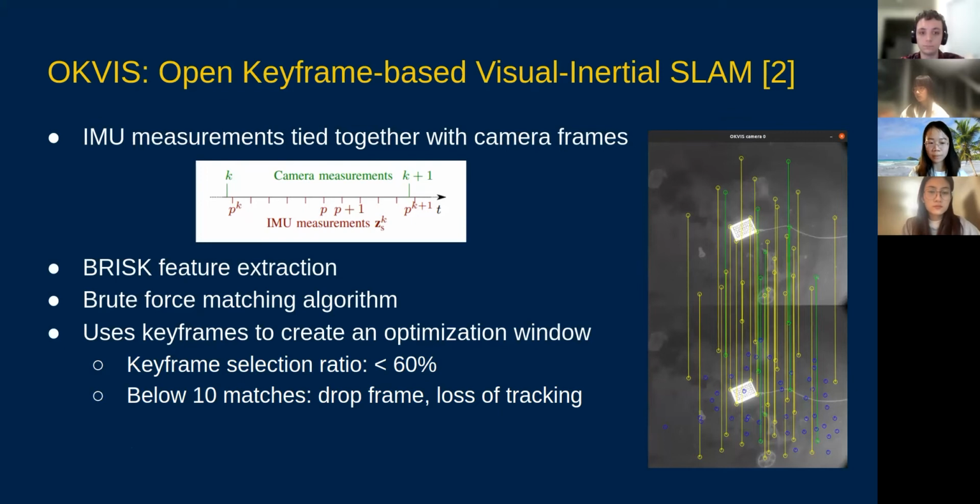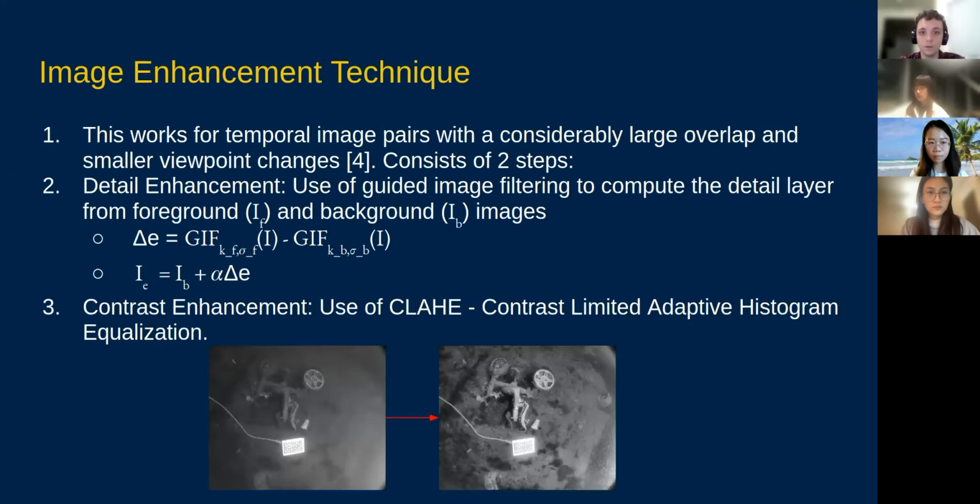The underwater application has turbidity and lighting issues, which can lead to fewer feature matches. So we integrate the image enhancement model to solve this. To improve ORB-SLAM3 and OKVIS, we implemented a real-time image enhancement node for each algorithm. Here, our image enhancement technique is described.